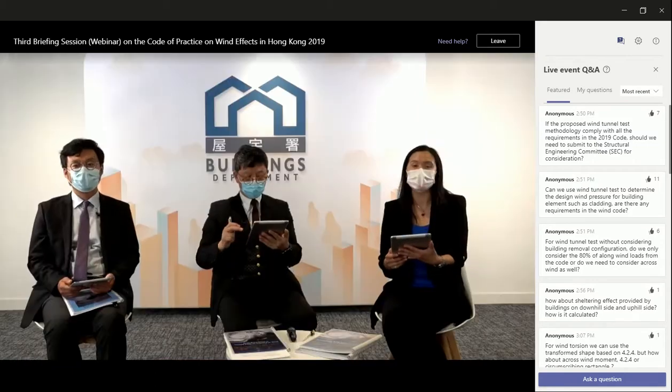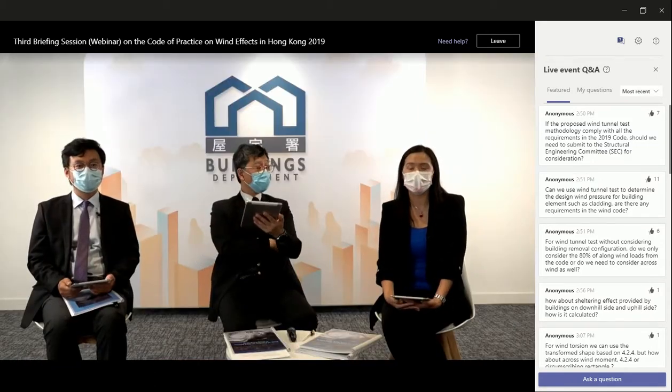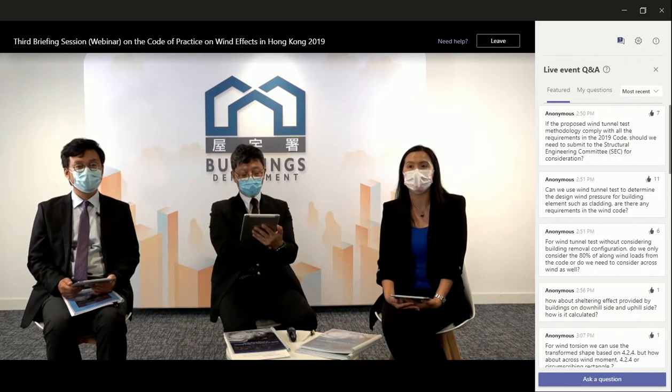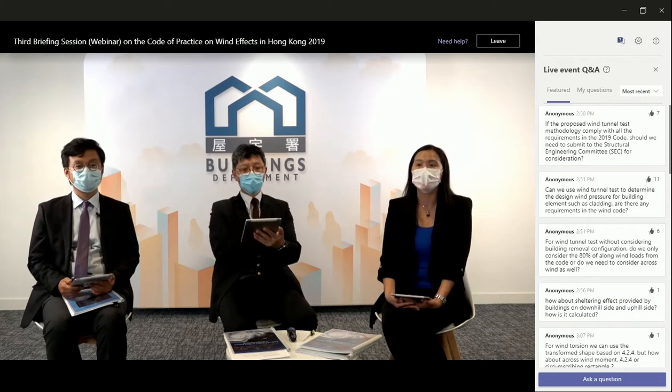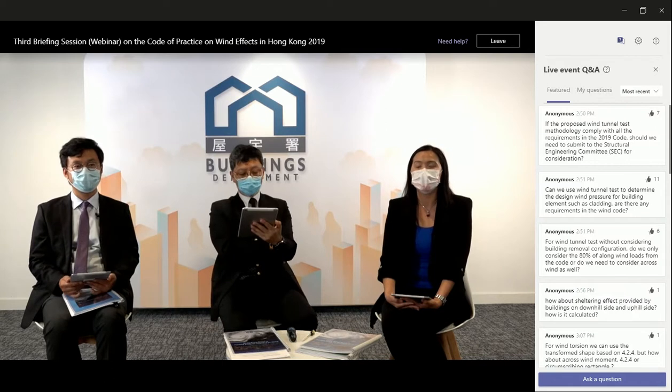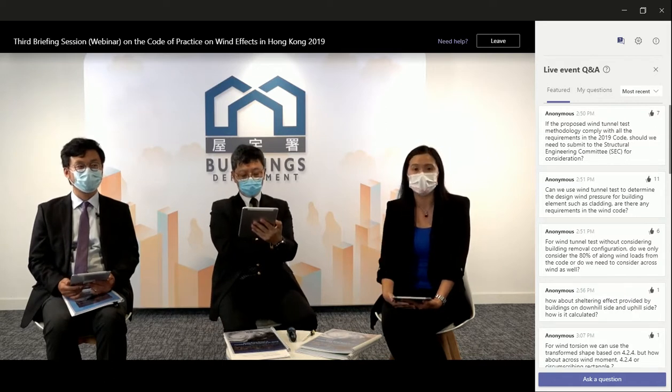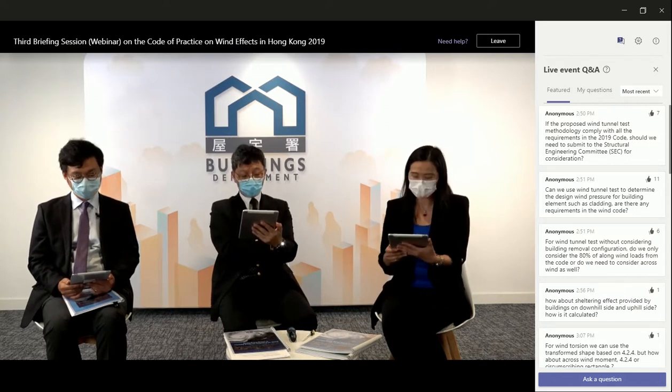Yes, actually currently we accept both wind tunnel tests based on force balance to calculate the structural load and the building response of the structures, and also we accept the pressure tap integration method so that the wind pressure of the building facade can be measured.